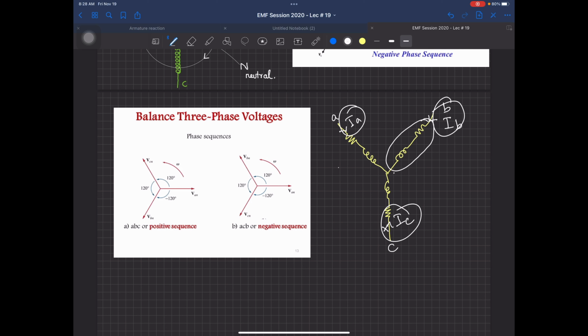When the machine rotates, maybe in 2/3 of the portion it gives you one torque, and then in the last 1/3 it gives a different torque. So there will be jerks in your motion, which tells you that your machine has a problem inside its winding or impedance.